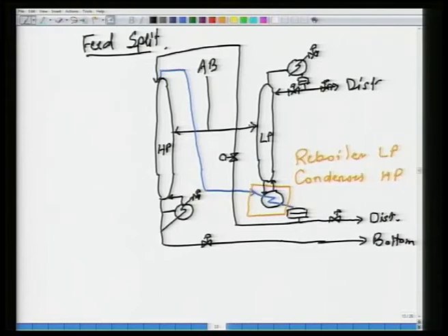Okay. So, on this T there are 3 streams, of which any 2 will have valves, the third will be dependent. Okay. So, let us say I just draw those 2 valves in this way, there is a reason why I am drawing it like this. Okay. So, is there a valve on this blue line?